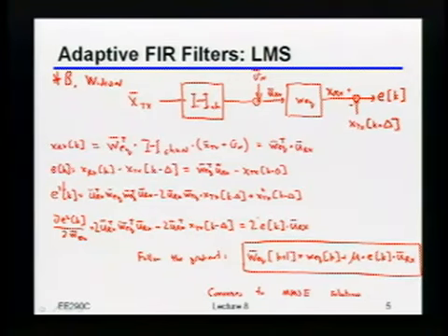In this particular example, this happens to converge to the MMSE solution. And the reason for that is because when you correlate your errors against the input to the equalizer, both of them actually contain the noise. So you actually do see the effect of the noise, and you try and minimize that. We'll see that in more detail in 1 second.